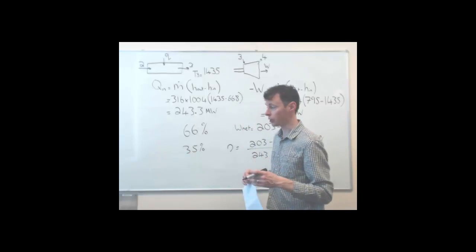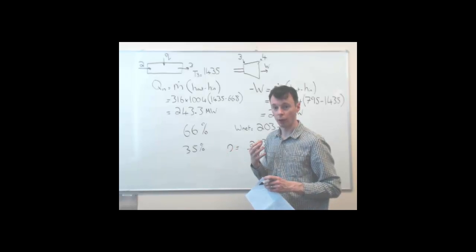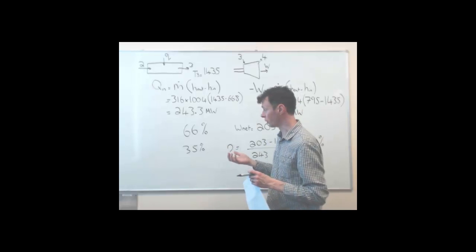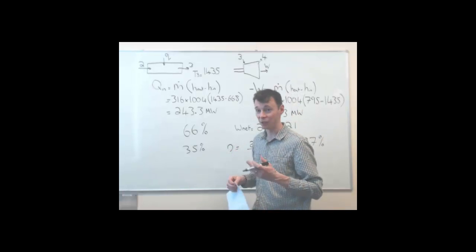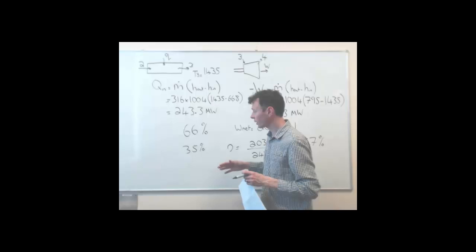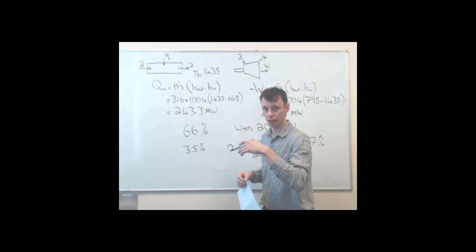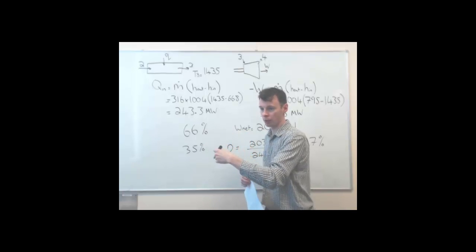And these are the ones that again just use a standard single cycle, whereby either coal is fired in a boiler or you have nuclear fission, and then that heats water in a boiler, creates superheated steam, and it's just a single type cycle.